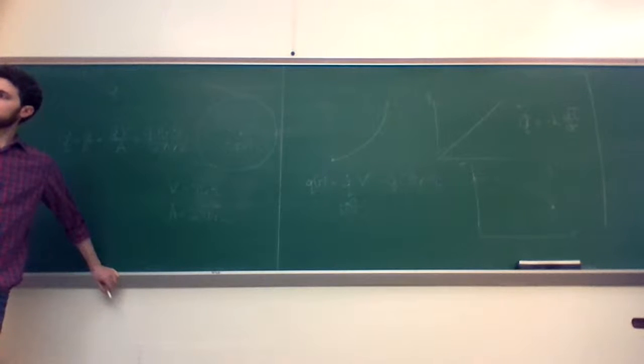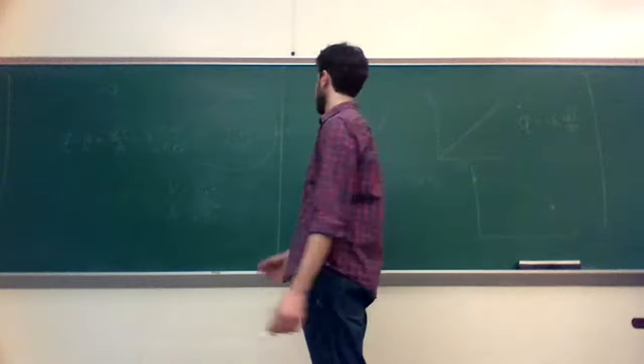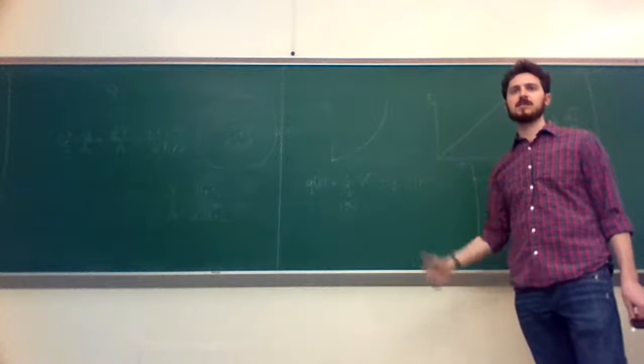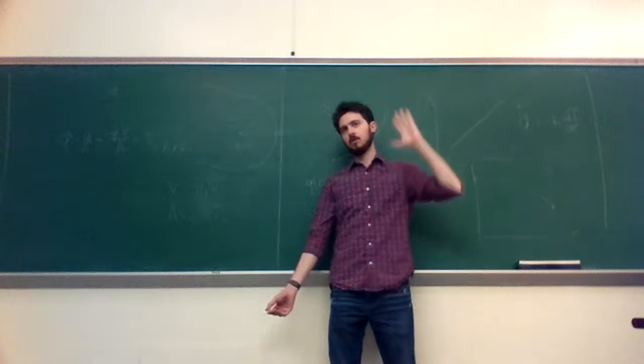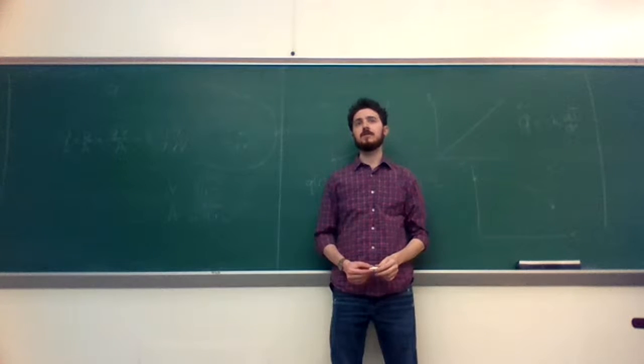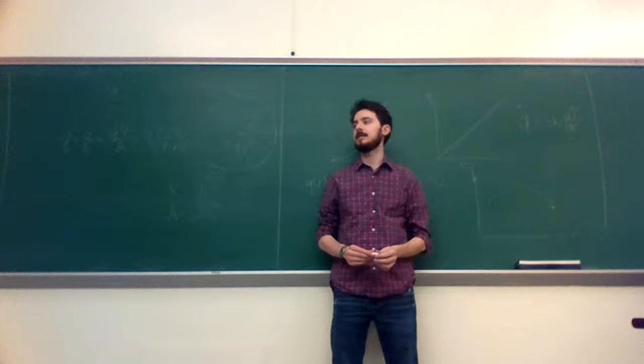Can your shapes look different if you have the opposite sign? If you had negative energy generation, which I think, for me, I did it out with the differential equations, and I ended up having a lot of constants, but I didn't know the sign of. Certain constants always have the same sign. Thermal conductivity is positive, right? And the reason that there's a negative term in Fourier's law is because by convention thermal conductivity is positive. If thermal conductivity were negative, what would that mean? That would mean that heat would spontaneously flow up thermal gradients, from cold places to hot places, right? Now that doesn't actually break the first law, because you can still have conservation of energy if heat's flowing in the wrong direction. It breaks the second law, right? You'd have entropy spontaneously decreasing, which wouldn't be good for the universe.